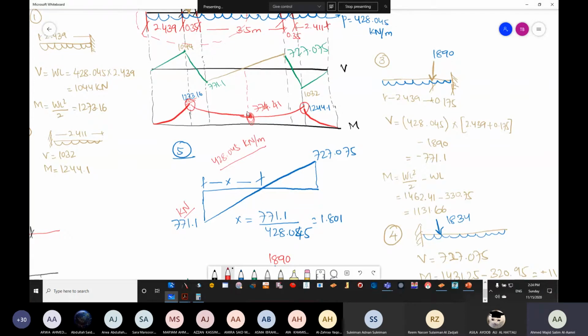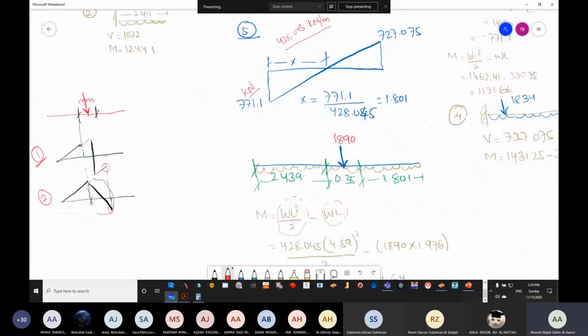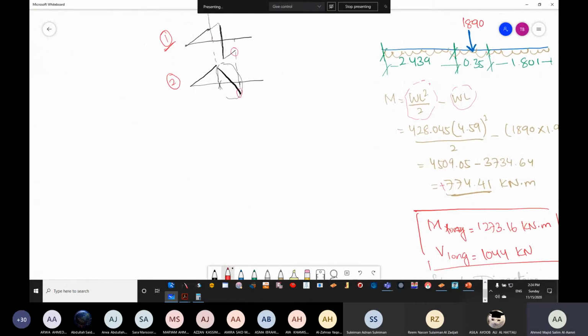Okay, so what do we have in this case, which is a very rare case for a combined foundation, is that we are having a full top bending moment, and the reinforcement is only going to be in one direction. So once again, the regular combined foundation will have a bending moment in this way. Once again, sign convention can change from one reference to another. But what do we have? We have span moment, and then we have support moment. And normally they will be in different directions.